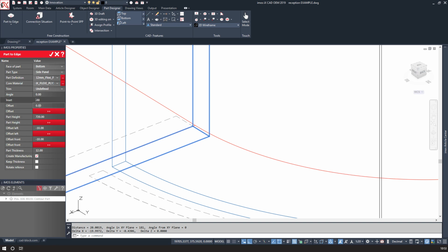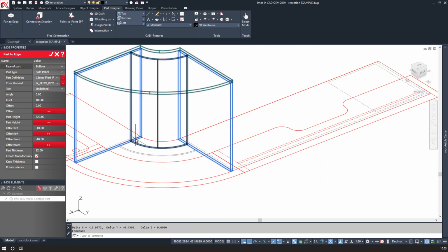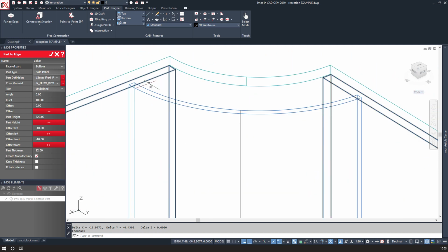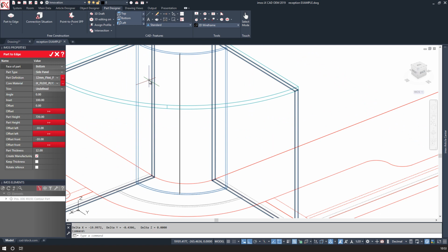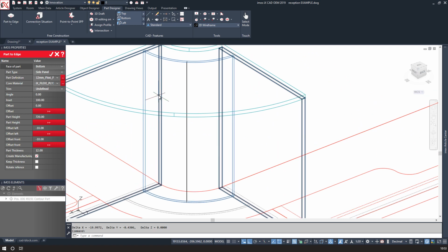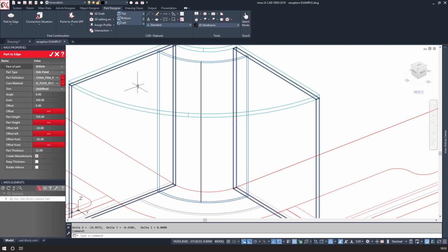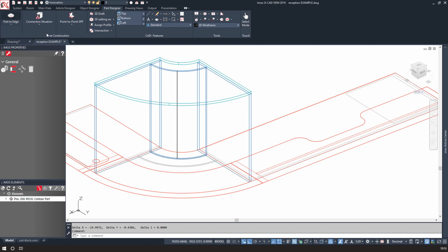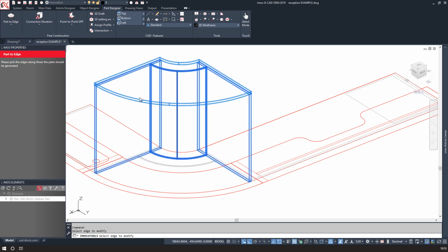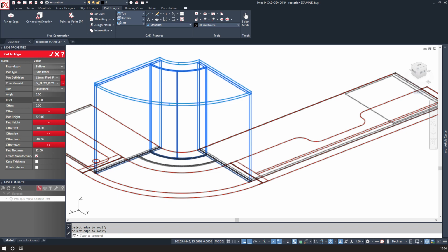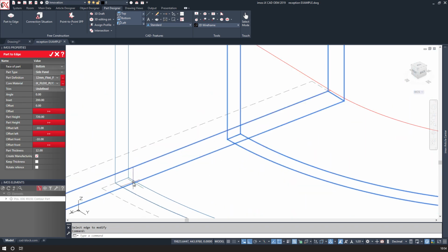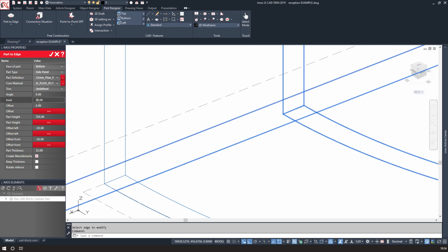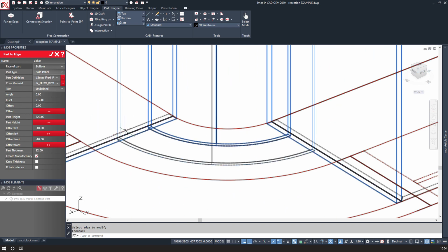This is pretty easy to just take some measurements and tweak this now. So I have my first curved piece of 12mm flexi-ply inserted. I'm going to need the second piece as well, so I can have a front and back section as per the drawing. I'll use part to edge again, and again select that rear edge. It'll remember my settings, and then I just need to offset that, the additional 112mm. Yeah, I need to push that out a bit further. That's better. Great.